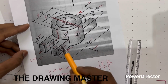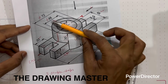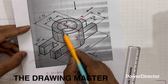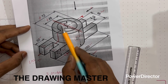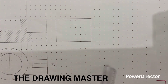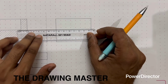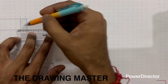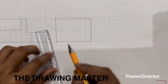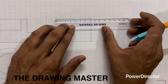Now the second part is to identify the cavity. The second step is to identify the cavity about this cutting plane. So when you cut this object through this path, about this cutting plane, this will be the cavity. This is 48 and depth 24. So here we can take the projection. This depth is 24 and diameter is 48.